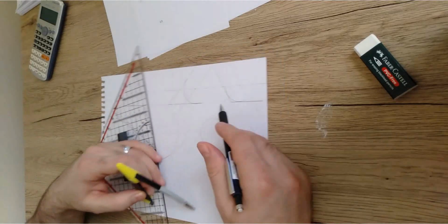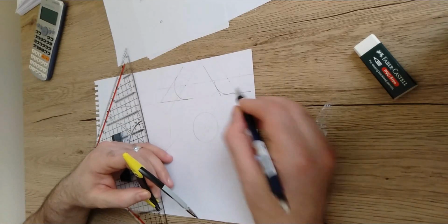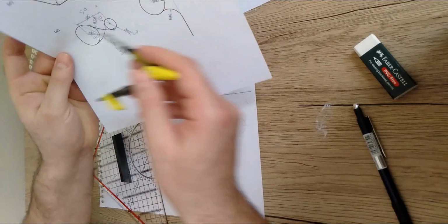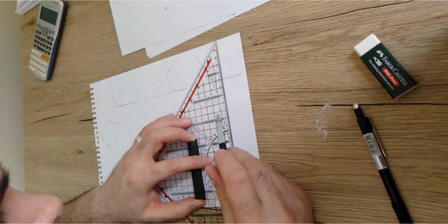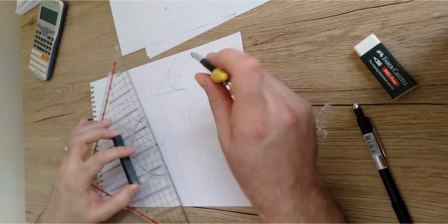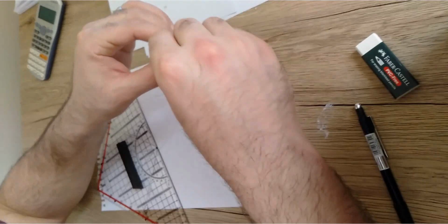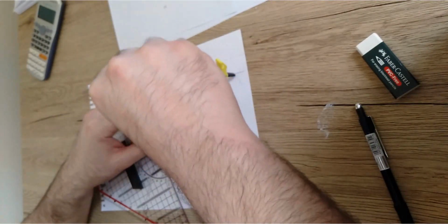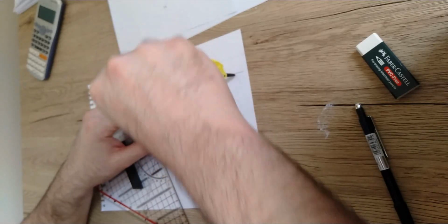So I do have one locus here, and there is another locus. Both are going to intersect at a point. This point should be the center point that I'm going to use to draw the first curve with a radius of 50. So I'm just going to draw the first curve with a radius of 50. Fix from this center point this way and draw the curve. If your measurements are accurate, you're going to find that the tangency will be perfect as I got it here.